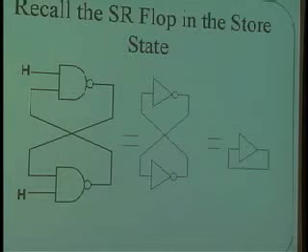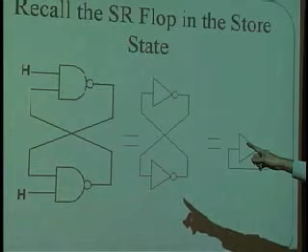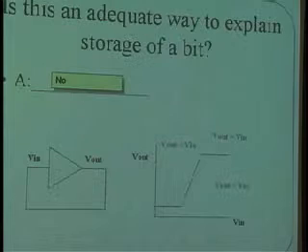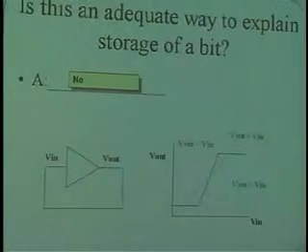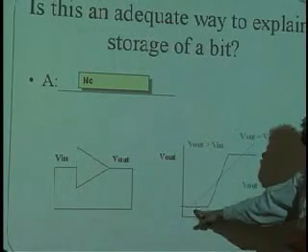And you remember the simple memory element, the set-reset flip-flop, and that with two high values on its inputs, that is the same circuit over there with the NAND gates as this one over here is with the inverters, which is really the same circuit as this buffer with just some positive feedback around it, and that buffer can in fact exist stably in one of two states. One is the high state, and the other one is the low state.